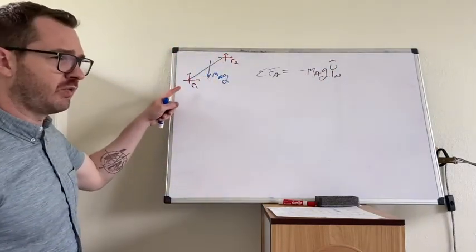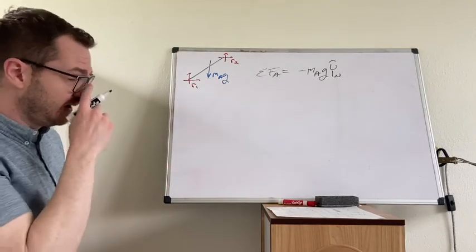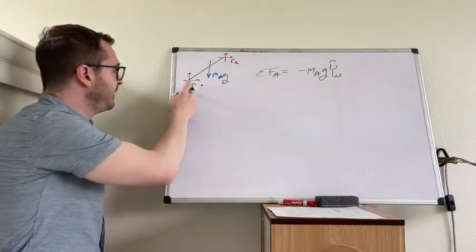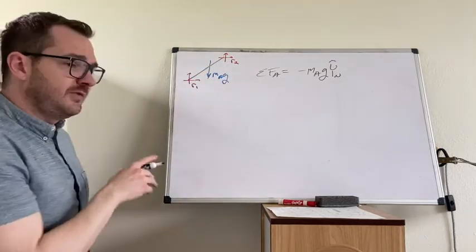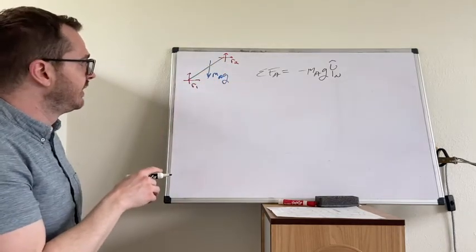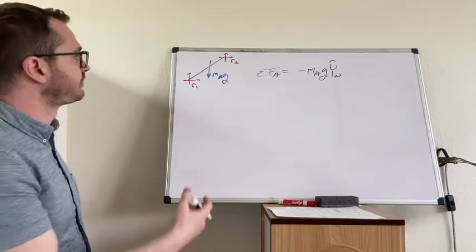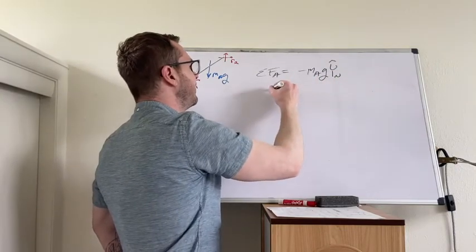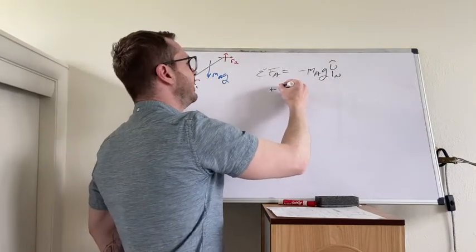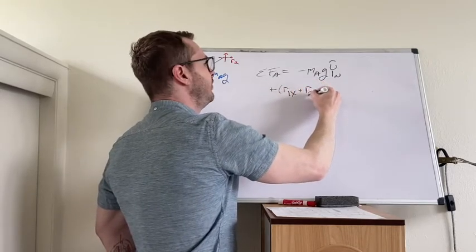What are we going to do with R1 and R2 though? In the last example we did these pin joints in the inertial frame. Let's do something different. This time, let's put it in the body frame and let's see what happens. So I'm going to come here to the top. I'm going to say there's gravity, and then there is also R1x and R2x.